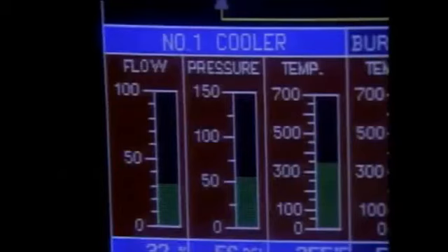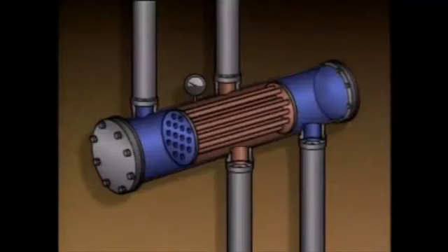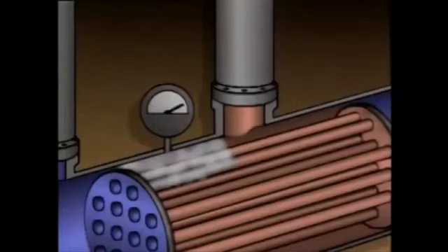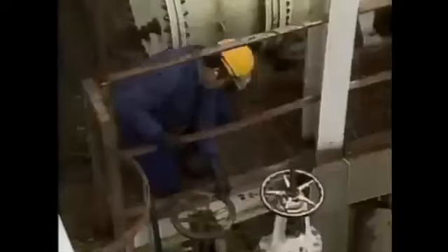There are also situations where the pressure inside a heat exchanger may be affected. For example, this can occur in heat exchangers that are used to condense process vapors. In this situation, non-condensable gases partially fill the unit, reducing the amount of heat transfer area that the process vapor can come in contact with. In turn, this reduces the amount of vapor that can be condensed. The flow of vapor will start to decrease, and the pressure inside the unit will start to increase.